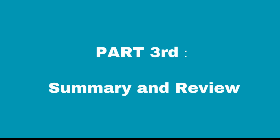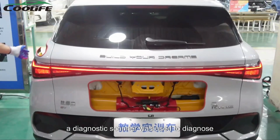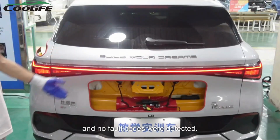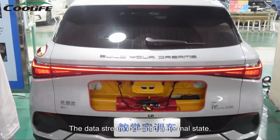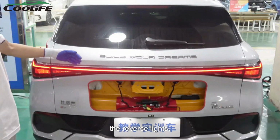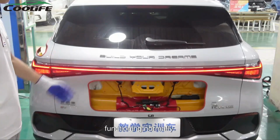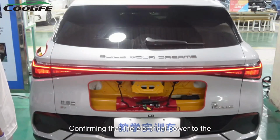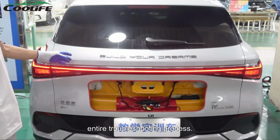Part 3. Summary and review. First, a diagnostic scanner was used to diagnose the vehicle, and no fault codes were detected. The data stream indicated a normal state. Upon inspection, the reverse lights, fog lights, and position lights were all functioning normally, confirming that the electrical power to the lights was intact. Let's review the entire troubleshooting process.